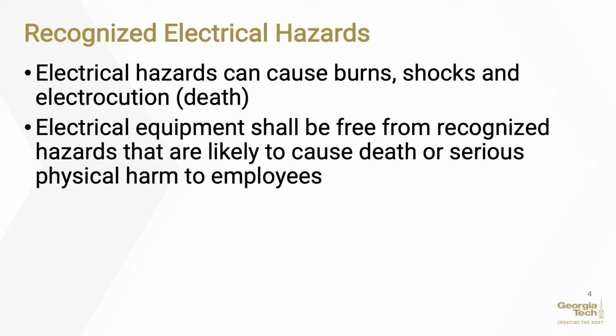Never operate electrical equipment while you are standing in water. Never repair electrical cords or equipment unless qualified and authorized. Have a qualified electrician inspect electrical equipment that has gotten wet before energizing it. If working in damp locations, inspect electric cords and equipment to ensure that they are in good condition and free of defects, and use a ground fault circuit interrupter or GFCI. Always use caution when working near electricity.